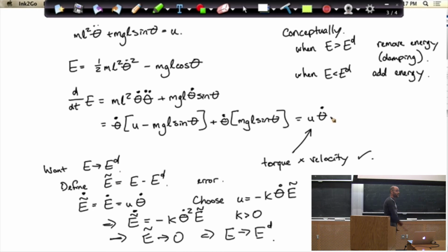And in fact, that margin is actually easy to make quite big, right? If you think about it, the controller I'm doing is just applying damping if my proposed energy isn't quite right. So it's easy to apply damping even if I don't know the system exactly. I'm just taking out energy, or I'm applying energy. So this is one of the good things about the controller: it's relatively insensitive to the parameters.